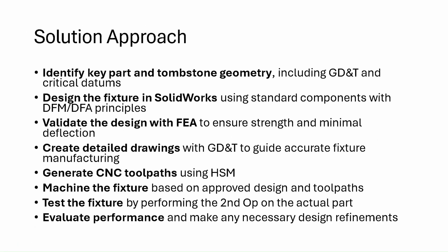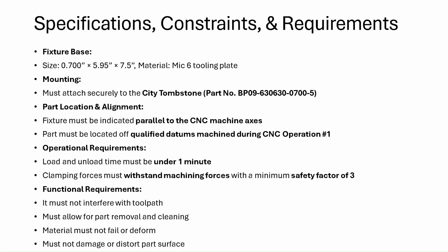Then for our solution approach, we will identify key part and tombstone geometry, then design the fixture in SolidWorks, then validate the design with FEA, then create a detailed drawing with GD&T, then generate CNC toolpaths, then machine the fixture, then test the fixture, then we evaluate the performance of the fixture.